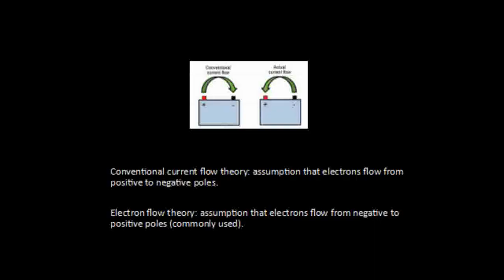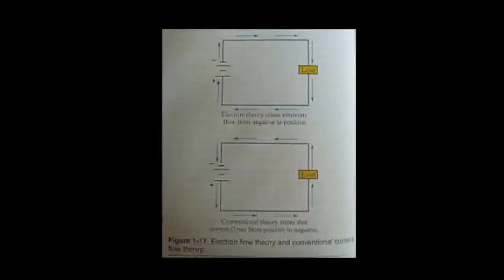For over 150 years, all circuit designs have been based upon the old conventional current flow theory. Many circuits and devices still used today are based on the conventional theory. This text uses the convention that will make the concepts in each example most easily understood. Most of the figures in this text show electron flow, regardless of which theory is used to explain the phenomena of electronics. The most important point is that the correct polarity must be maintained when building circuits with devices that require a definite polarity. Examine each example for polarity markings.